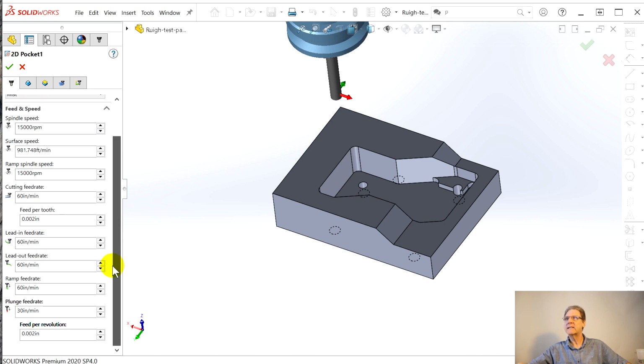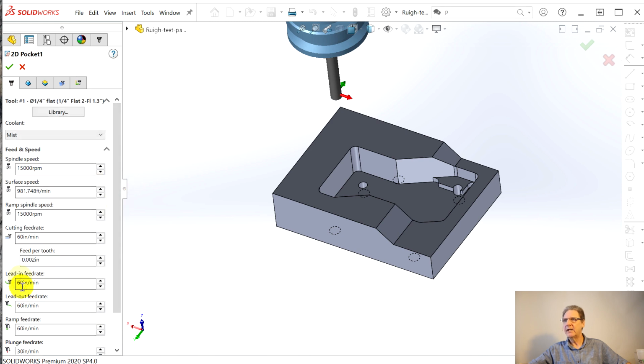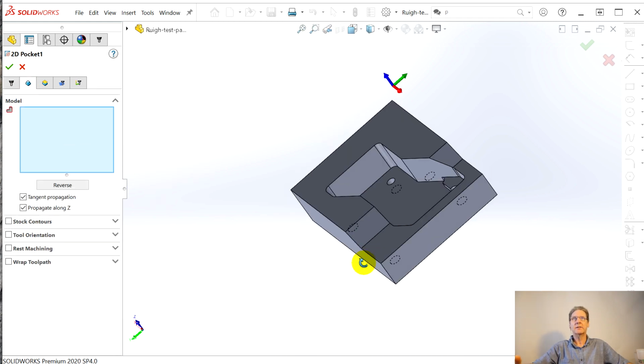No. So that's actually, I changed one of these to 16,000, right? I thought it was spindle speed. So apparently it looks at the previous tool, but doesn't inherit what you changed from that one operation, if you changed anything. I like that. It brings in not the tool state from the last operation, but from the library where you store all these speeds and feeds. That's fine.